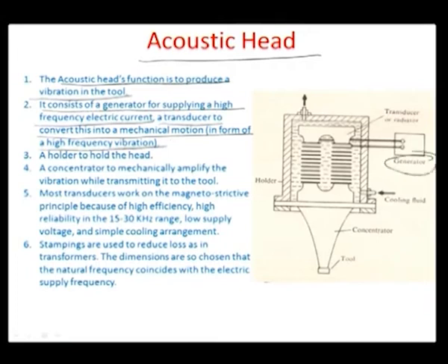This right here is the generator, okay, and this is the magnetostrictive material, the transducer, okay, which is actually having a coil. You can see this coil here coming from the waveform generator, meaning thereby that if a high frequency is given to this coil, then there is a change in the grains, and so there is always an external magnetic field. So, supposing there is a dipole moment set like this, north south, something like this, and then there is an externally influencing magnetic field.